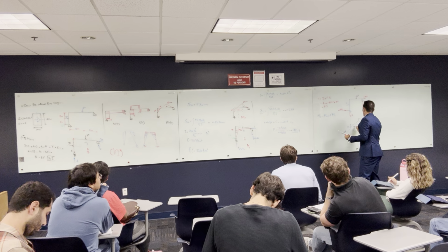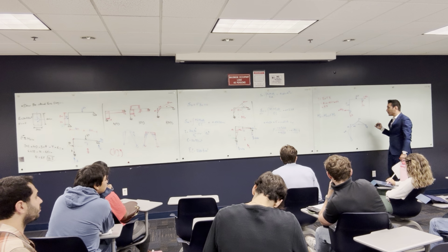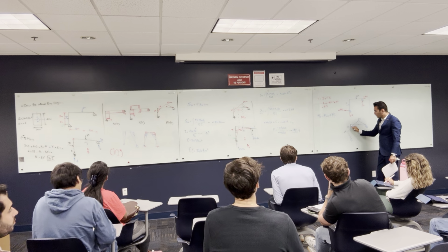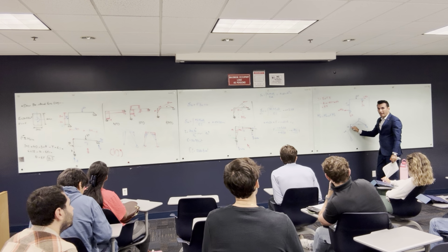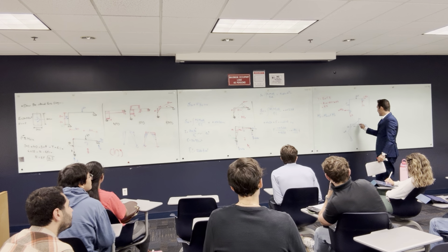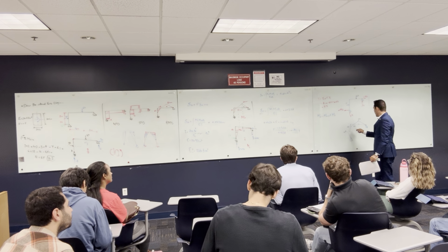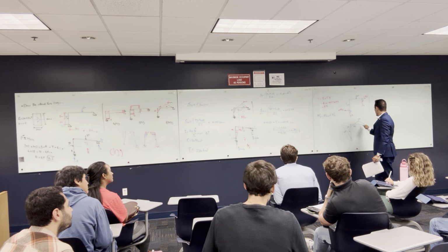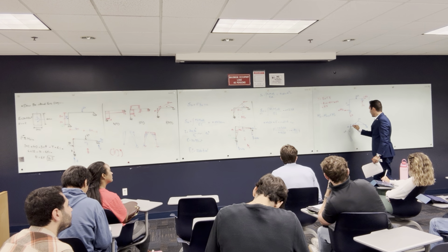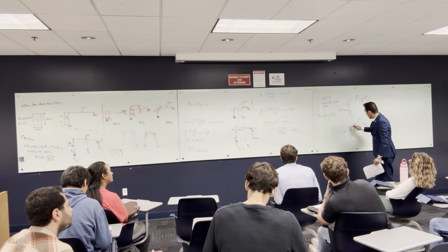And this definitely should be equal to 4.2 without any calculation. Why? Because if this is 4.2, this has to be 4.2. They have to have the same bending moment for the stability. So this is positive, and this is negative. Sorry, this is positive too. So I'm going to make this, and these are the negative bending moments.